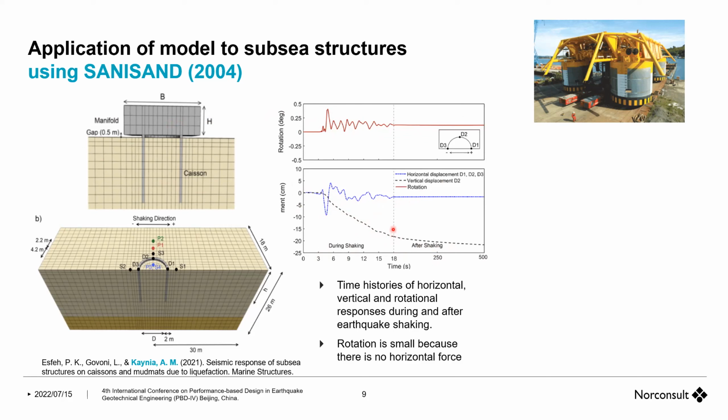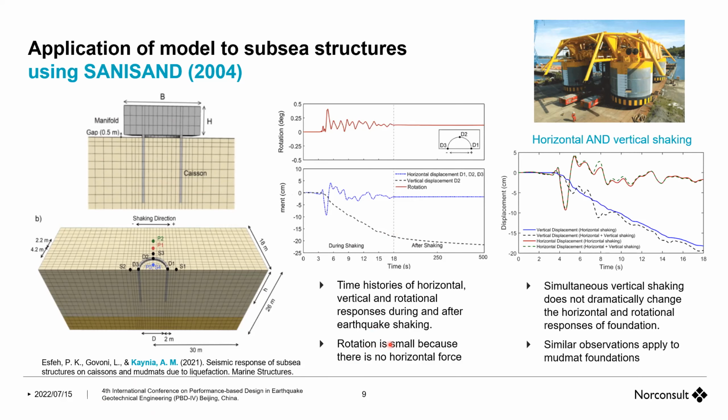not dramatic. And I was very interested in doing this study because during the time that I was very much involved in offshore structures, there was a lot of concern about subsea structures. What happens to them if liquefaction happens? Actually, these structures have large mud mats and foundation, and the net effect is some slight rotation. So maybe liquefaction is not as scary as it sounds.